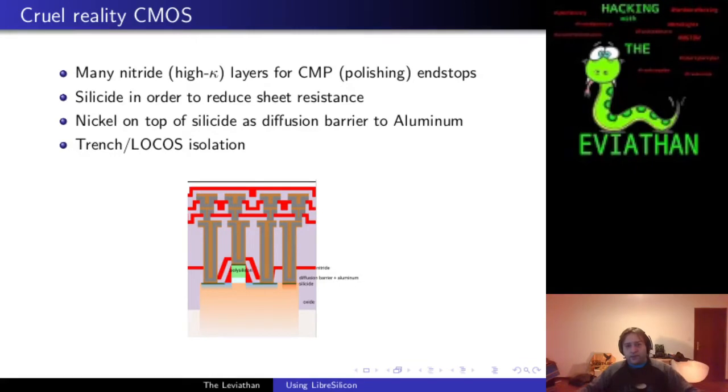It doesn't matter whether you perform very large silicon integration, or VLSI for short, which works down to 500 nanometers or 350 nanometers, which can still be isolated using LOCOS, or whether you are doing ULSI, ultra-large silicon integration, which is needed for very, very small feature sizes, like 24 nanometers or 65 nanometers, where LOCOS doesn't work anymore and you have to use STI, shallow trench isolation.